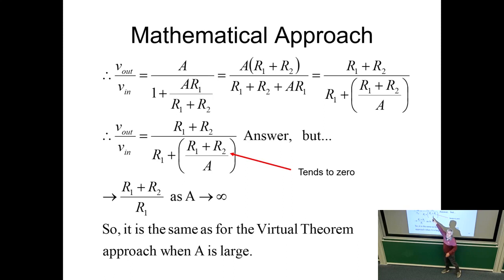What we would do is make A frequency dependent. You'd redo this calculation lots of times with different frequencies, and you will find that it goes flat, flat, flat, flat, flat, and then falls away, like you did in the lab. Yeah. So what you're saying is, as long as I can assume that frequency is not having an issue on my gain system, I can apply the virtual Earth and everything is hunky-dory. If frequency is an issue for me, then I need to consider what happens at high frequencies, and are my assumptions still valid? Most of the time they will be, but